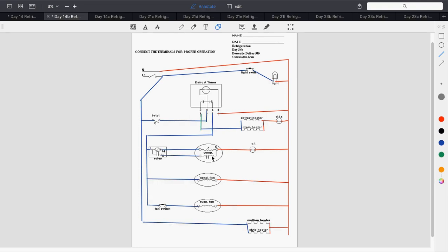Current coil. It is the only time you are going to see a load in series with a run winding. That coil is a load, but the wire on that coil is so big, as I'm pretty sure I showed some of you in shop, that it doesn't really have any resistance. It just energizes, creating a magnetic field based on current. When the motor first starts, there's some pretty heavy current in there.